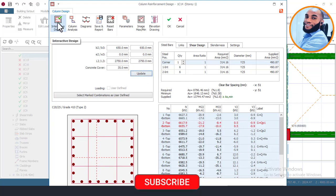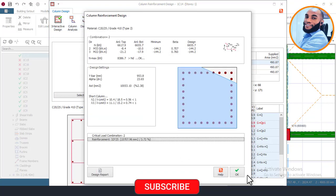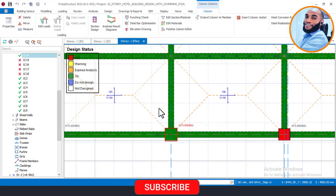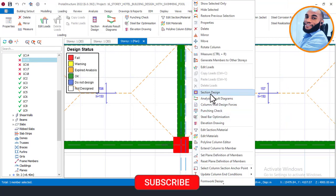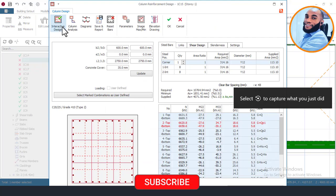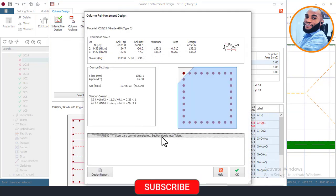Okay, so I'll come down and click here, reset first and then design. The number of bars will be given to me, that's okay. I can now click okay here and okay here, that's fine. Okay, and I'll come again here, right click and click on settings design, and then let me check again why it's failing. That should be on the size too. Yeah, the size, you can see here right now section size is insufficient. Come here and then increase.